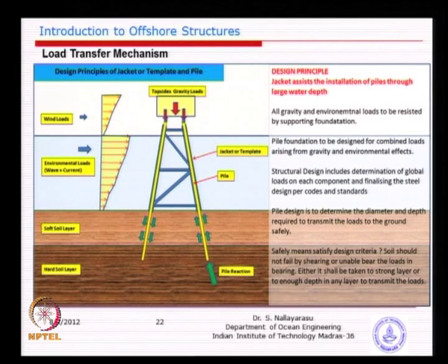The horizontal load multiplied by the height of the center of load will give you the overturning moment, divided by the spacing at the seabed will give you the reaction. Very simple calculation. So the larger the width at the base, you will find the smaller the load transfer to the soil and the foundation. So that is the idea behind it.